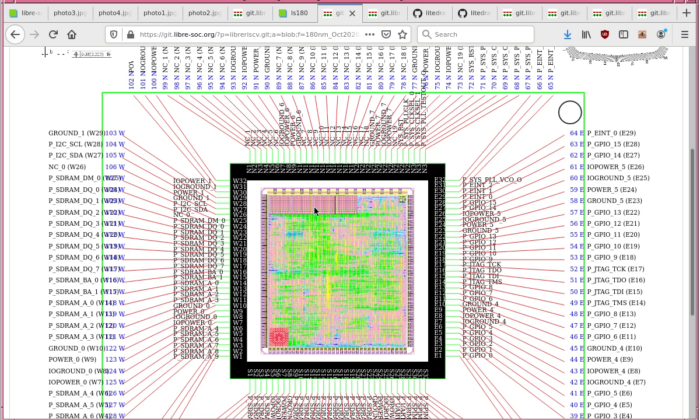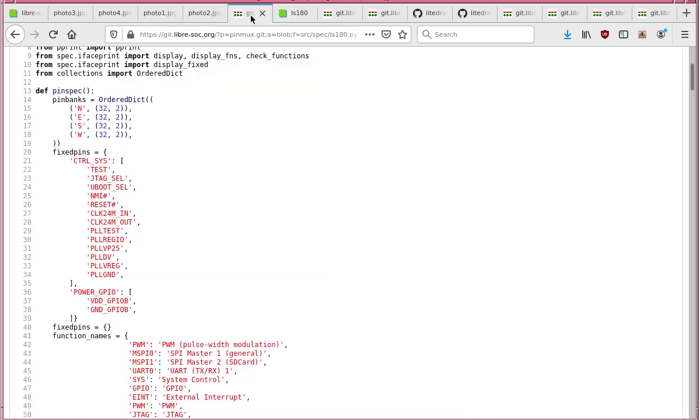This is at the top left, along the top. There are the 4K SRAMs. That tiny block in the top right-hand corner is the PLL, which was manually placed, and so were those 4K SRAMs, followed by automatic place and route of the rest of the 130,000 standard cells.